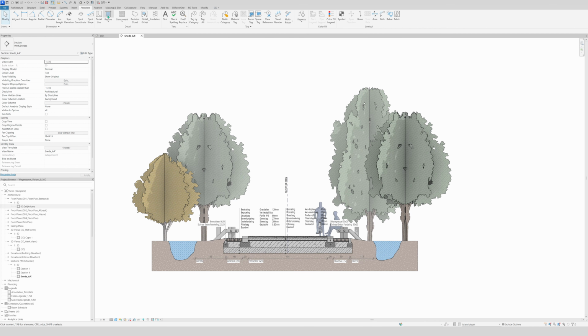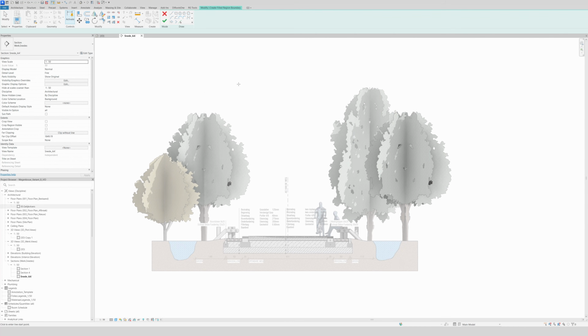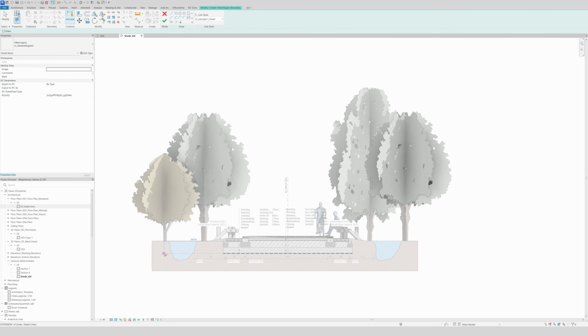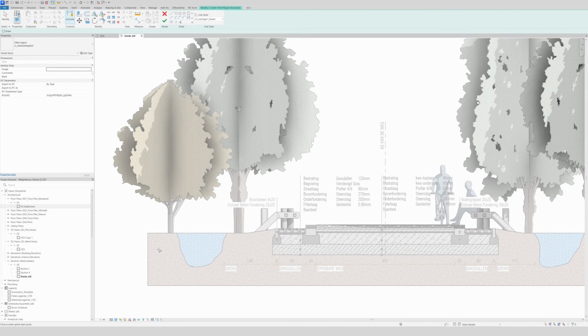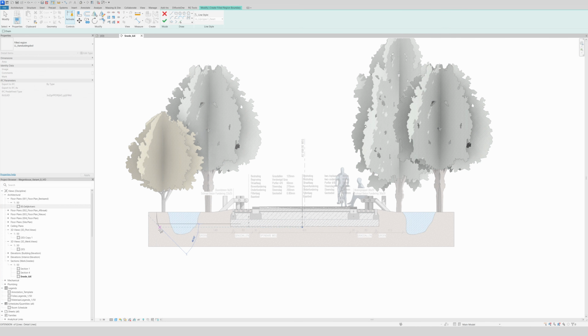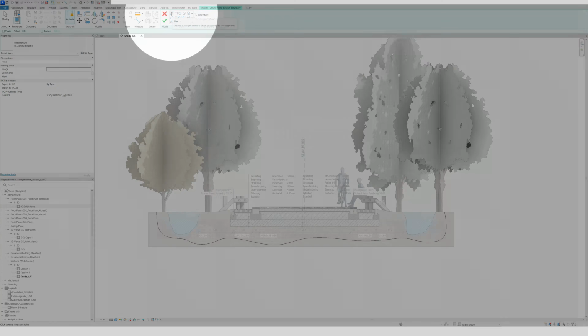We go to region, fillet region, and then we're going to draw a box over it. Just make sure you begin here and not above. You will see in a moment why. So we're just going to randomly draw it like this, up like this, nicely done. We can adjust it later on, of course. And now, oh nice, up like here. Then you click escape. Then we go to straight lines right here.